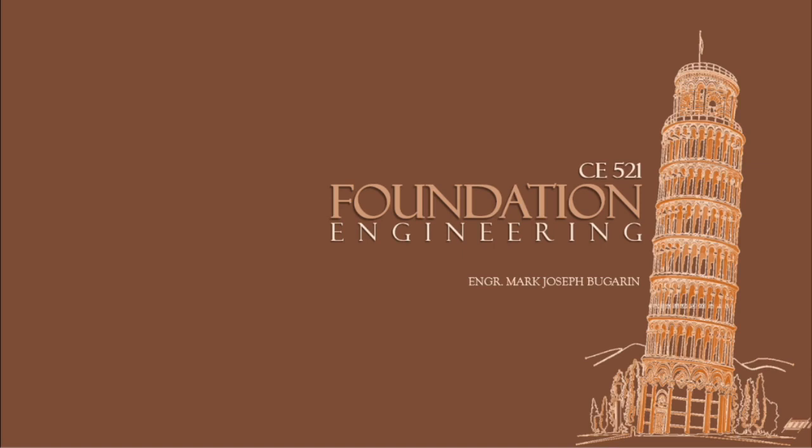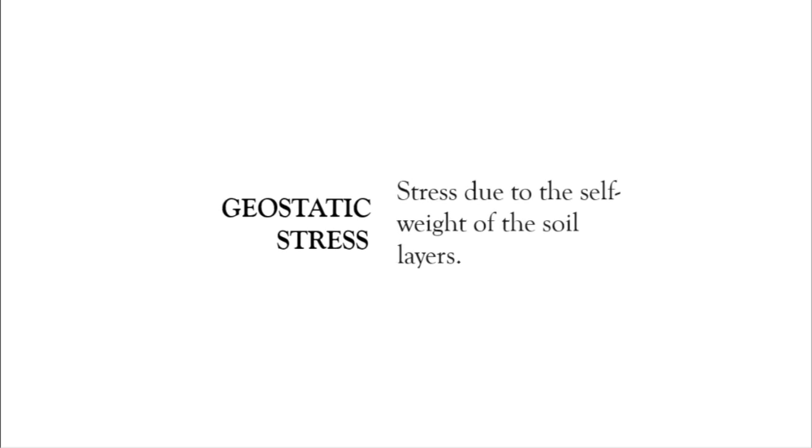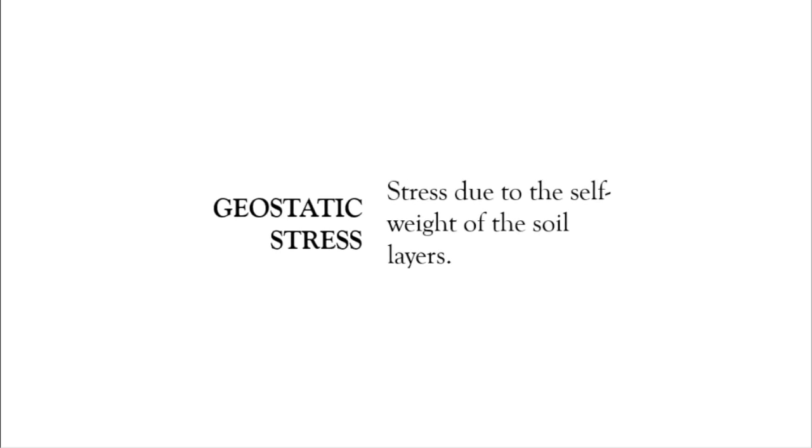All right. So the first topic we will be focusing on is the subsurface stresses in soil. We have what we call the geostatic stress. Geostatic stress is the stress due to the self-weight of the soil layers. In order to solve this stress, it is very important to first identify the properties of the soil that contribute to the geostatic stress, such as the specific gravity, the void ratio, the porosity, and most importantly, the unit weight of the soil.